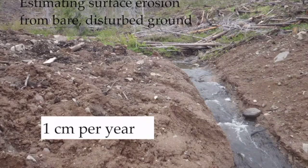Over 1 or more growing seasons, vegetation will also become established on most disturbed sites. Historically, workers used to leave the surface to harden up on its own, but now we know this isn't a good idea, as hardening up processes generates fines that get into our water systems and clog up spawning beds.